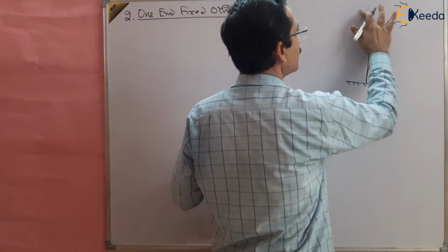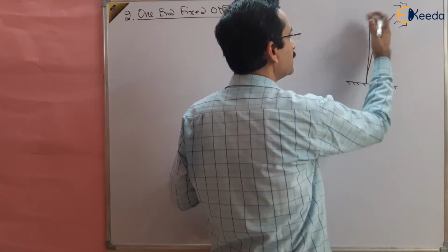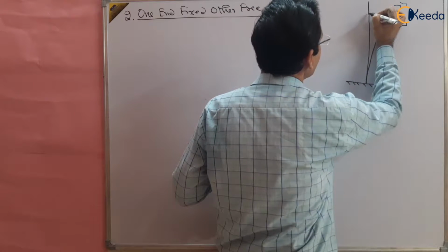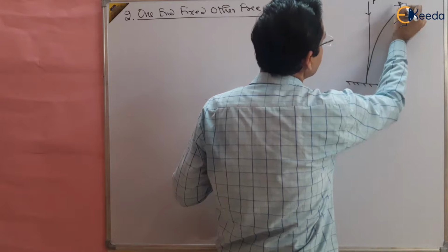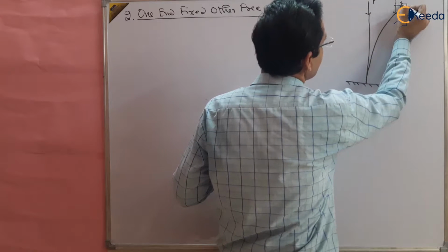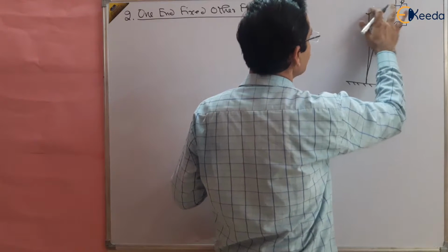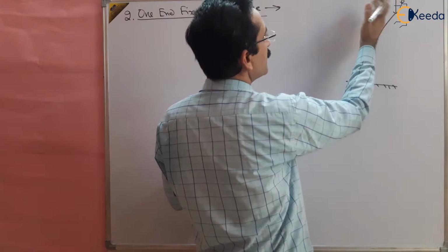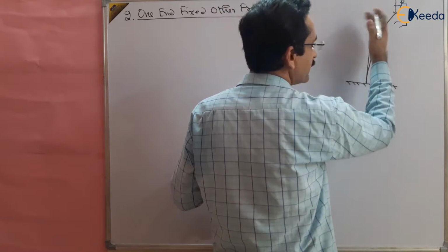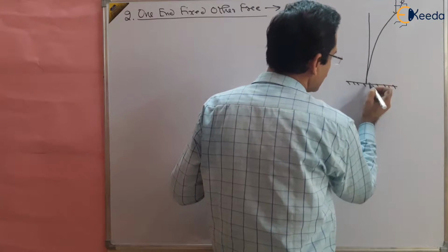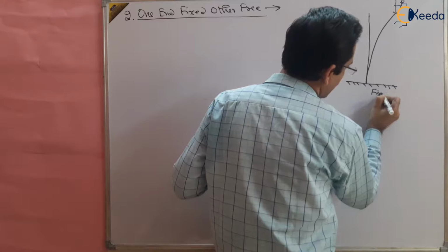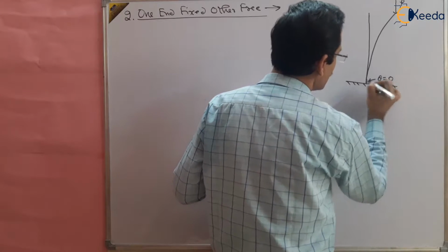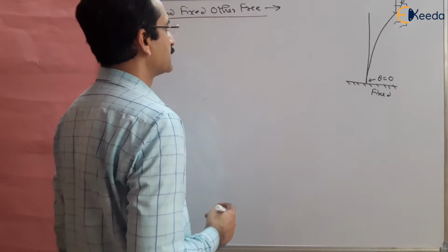This is the variation, the change in the deflection in the column, right? And we have applied load P here, and this load will move to this position, right? So this is the final position. This is the bending in the column, right? And this end is fixed, and the slope at this point, theta, is 0. You know that already, we have studied the boundary conditions for that.